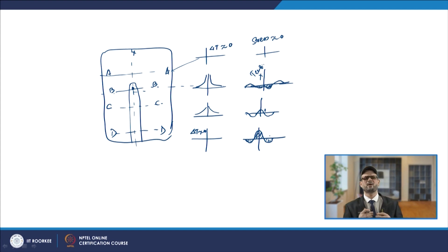So basically what we wanted to know, when we talk about the mechanical stresses, is that in those cases you have expansion as well as contraction going on. In those cases your stress pattern will be changing, and that will be the development of the residual stresses. If you talk about the other residual stress, that is your metallurgical residual stresses.